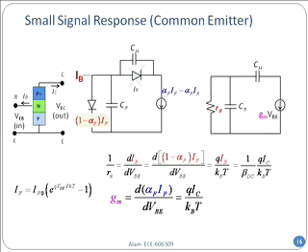What about gm, the transconductance? Well, you could again calculate alpha F multiplied by IF. Why do I just talk about alpha F multiplied by IF? I'm talking about the current source. What is the value of IR in the blue, in the equivalent? IR is 0, right? Where it's reverse biased. So the only part in the blue current source is alpha F IF.